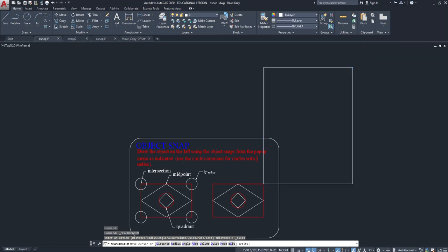All right, escape, escape. So with my lines, I move in the direction I want to go, I turn my ortho on or off, and I input a dimension, right? I can also click and just eyeball what I want my dimensions to be. I can then measure things to make sure that they're the right size, right? By using distance or measure, whatever option you want to use, okay?